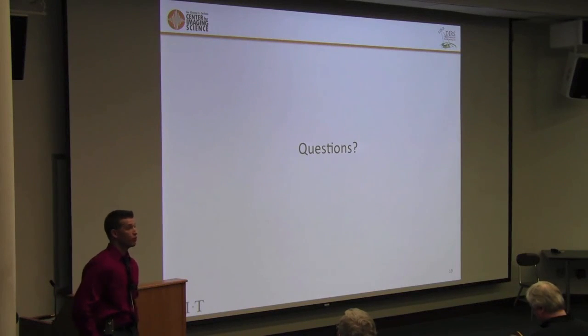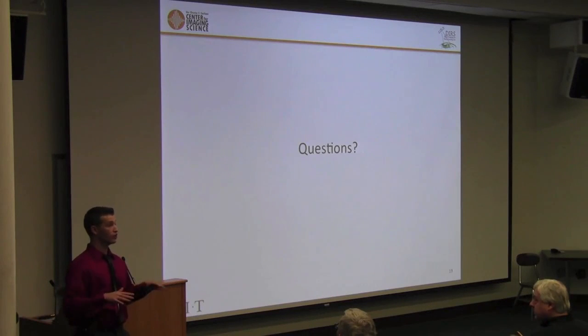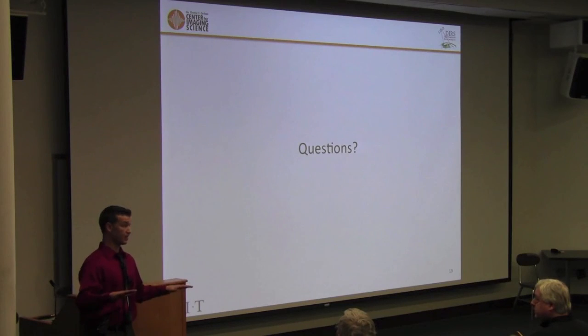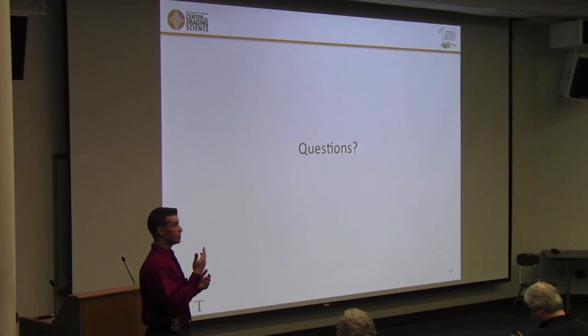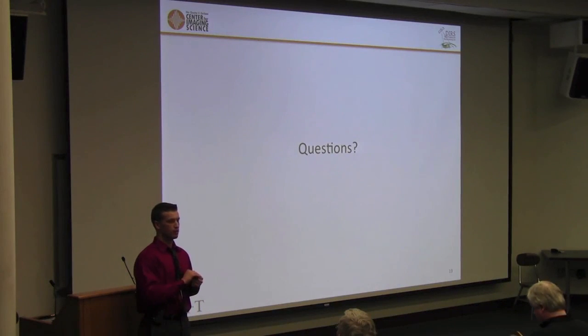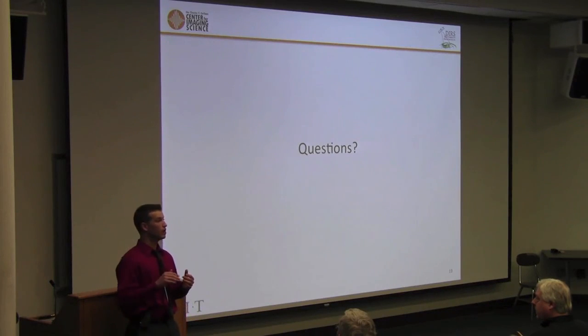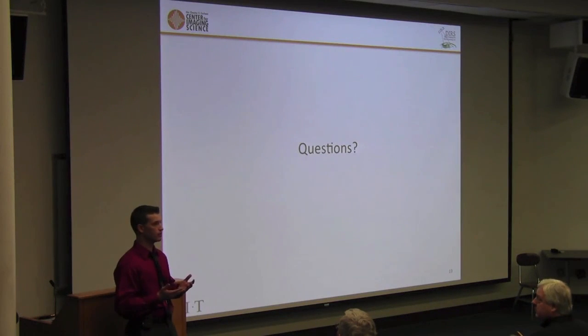Yeah, so that's an important point, and that was one that has actually been brought up before by some of the faculty, is also while you're leveling or while the system is taking the measurement, how you compensate for any settling that may happen. And that's something we're still thinking about. From the shaking and stuff like that with our stepper motors, what we've done is purchased fully integrated motors that actually have acceleration and deceleration profiles. So we can use those profiles to create nice smooth motions that limit that vibration throughout the system.